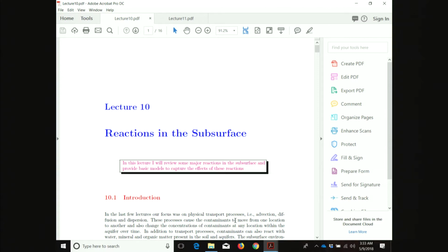So one was to do tracer tests. We can either do a forced gradient tracer test or a natural gradient tracer test. Natural gradients are obviously better than forced gradients, but a lot more expensive to do. Forced gradient tracer tests are done primarily because they're easy to do. But there are places where a forced gradient test is okay.